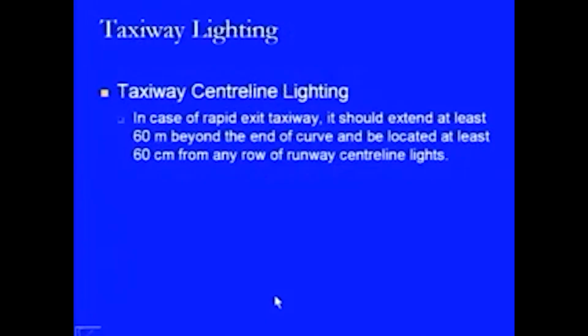The taxiway center line lighting in case of rapid exit taxiway should extend at least 60 meters beyond the end of curve and be located at least 60 centimeters from any row of runway center line lights.